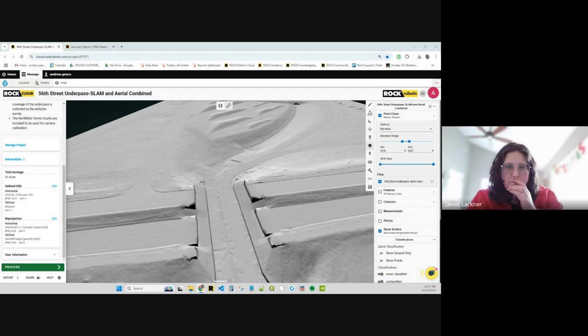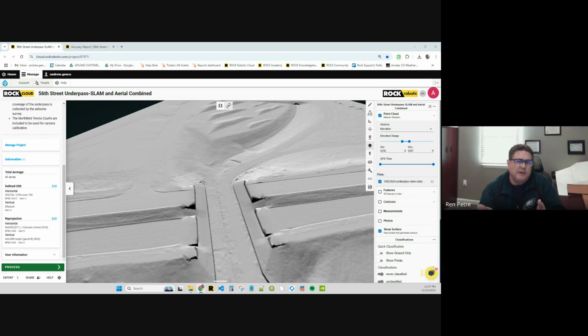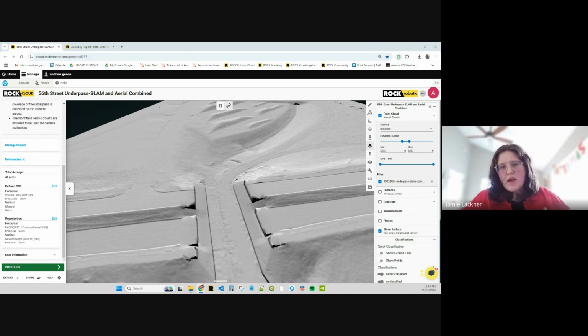I understand now what you're asking for. But most of them are like this. If it's a bridge or an overpass, you always want to show it the way you have it right here, with the ground elevation, and then the bridge is just a superimposed line over top of it. Yes, okay. And that's kind of what we'd love, if you just send us a note, or put in the notes, like, hey, there's a box culvert, retain the surface, or we care more about the underneath than the above.